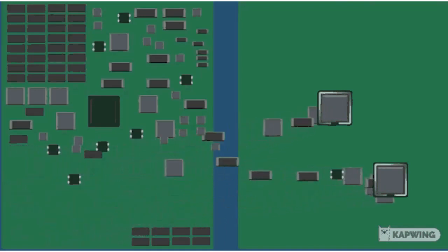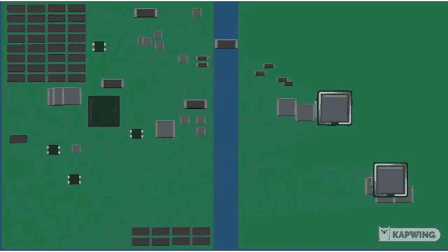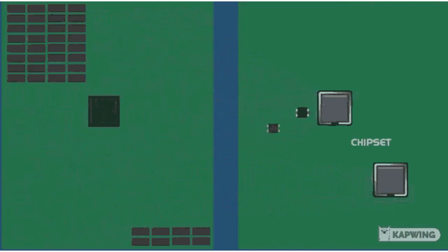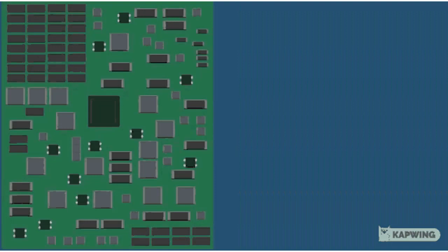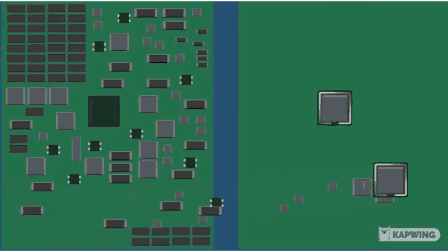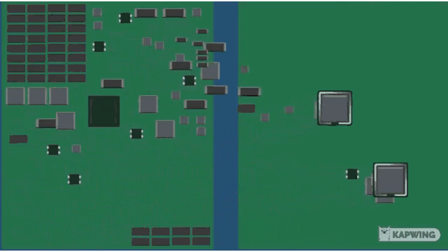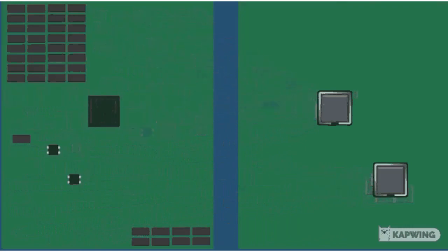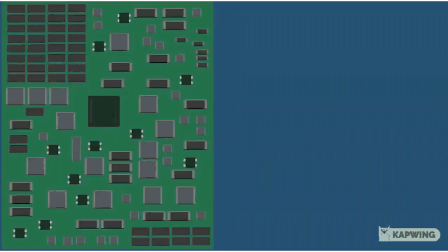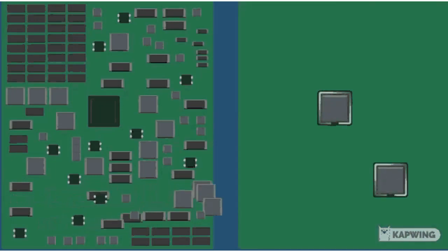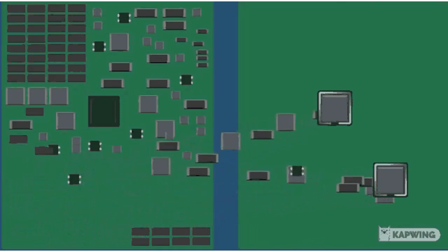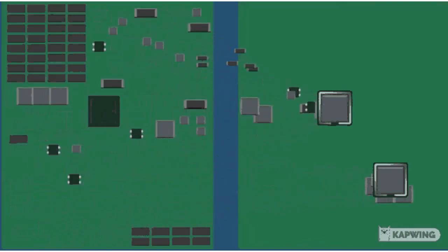While going on with advanced technology, computer engineers started to reduce the number of chips and have more in a centralized location. They have reduced the number of chips to do the same jobs and condensed them into a few chips, or what is now called a chipset. A chipset is a smaller set of chips that has replaced a large number of chips, and its job is to control data flow between the CPU, peripherals, bus slots and memories.